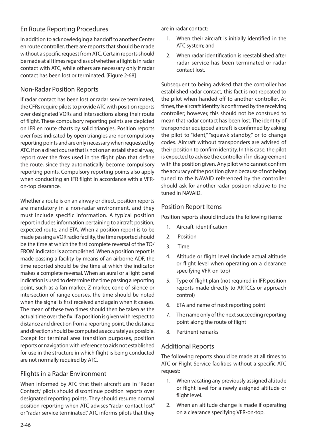For flights in a radar environment, when informed by ATC that their aircraft are in radar contact, pilots should discontinue position reports over designated reporting points. They should resume normal position reporting when ATC advises radar contact lost or radar service terminated.